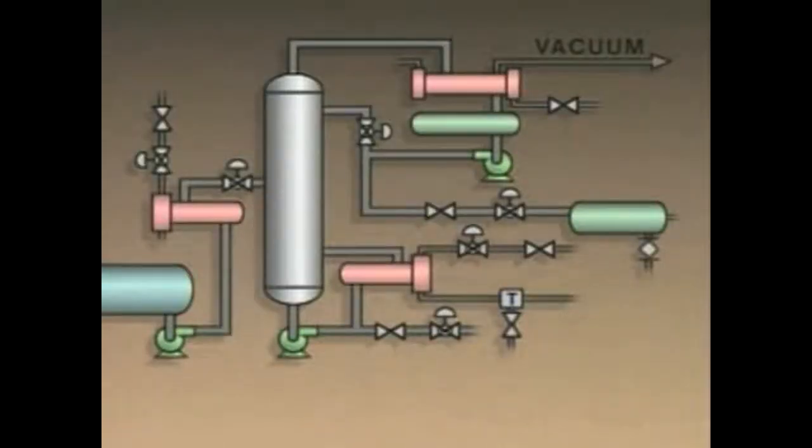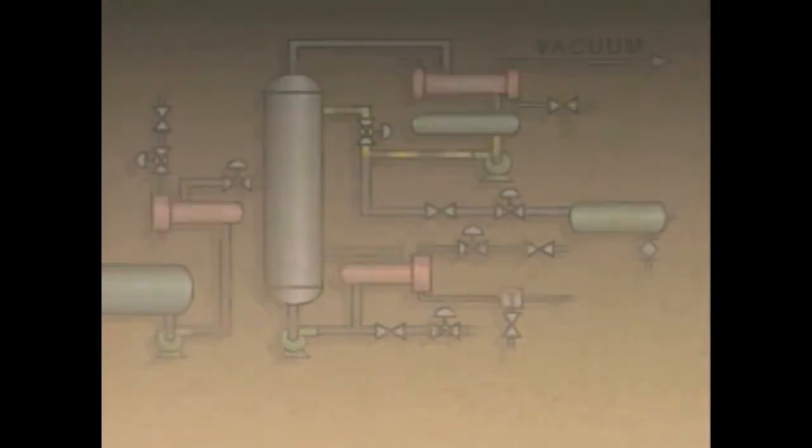In this vacuum distillation system, a long-term shutdown begins with the feed system. First, the steam flow to the preheater is shut off. Then the feed pump is shut off, while the feed control valve is closed. With the flow of feed mixture to the column stopped, the level of overhead product in the receiver drops. When the level drops past a specified point, a level controller on the receiver automatically closes the overhead product takeoff valve. This places the system on total reflux.